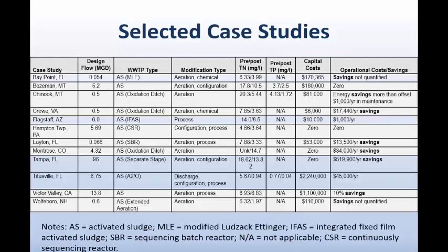Monitoring could be simple dissolved oxygen or redox probes, possibly wired into a more elaborate algorithm for determining on and off or variable aeration rates. So it includes both the control side as well as the ability to change redox conditions in reactors by throttling back aeration or on and off control of aeration, which requires the appropriate drives and so forth.